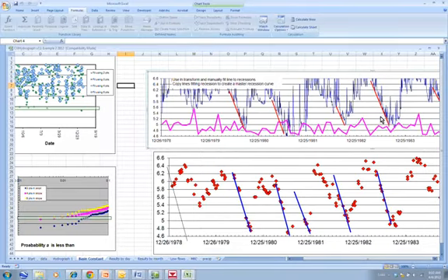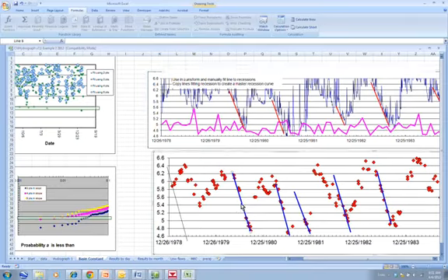But what we see in the data are places like this one, where we have a very nicely defined linear decrease when we plot the log of the flow rate as a function of time. So this we would interpret as a base flow recession. And these are as well, possibly. So what I've shown here is another look at the data, and instead of seeing all of the flows, these are just the turning points that are plotted. So it's just a little simpler, and we see that we have some negative slopes here that are fairly consistent.